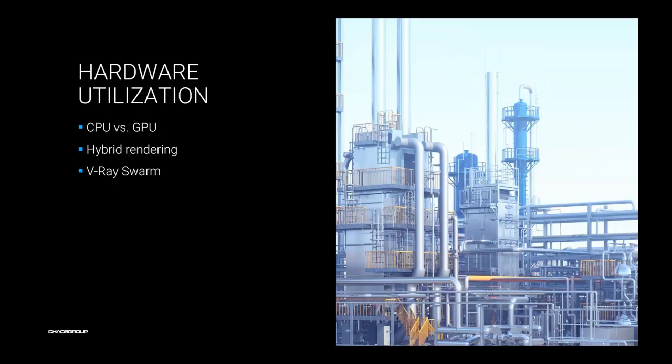There is also an option not to use your local machine, which basically means that you can set up the render settings, send the rendering over to be rendered on the other machines, and continue working using the full resources of yours. Note that to use Swarm on multiple machines, a render node license is required for each node, but since Swarm is also supported in V-Ray for SketchUp and V-Ray for Rhino, in case you use any of them, you can use them as render nodes.